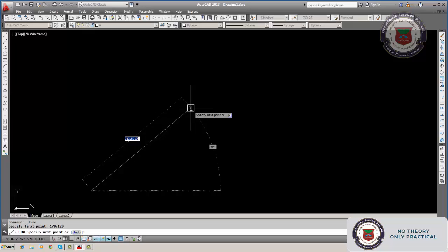Now we can enter, it is focused on the length, that is the blue color one as you can see. So this is focused here. It shows the length is now 730.527. If you click it here, the length of the line is 730.527. Suppose you want to have a different length, say 700. This is the point 700, and the angle shows 40.